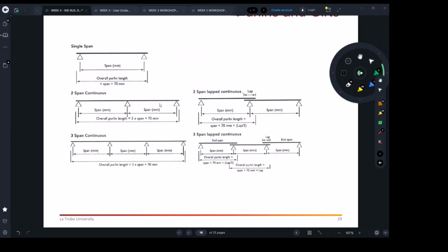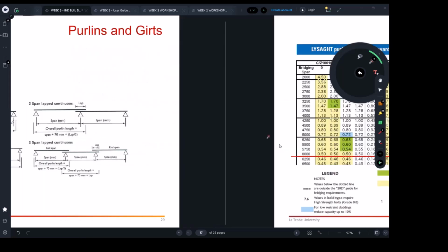Maybe sometimes in the city you can't bring very long trucks. It's very expensive and slow for them to maneuver and turn around. So usually you can bring those sections as smaller spans and then just do the lapping, but that's the only best option you have.